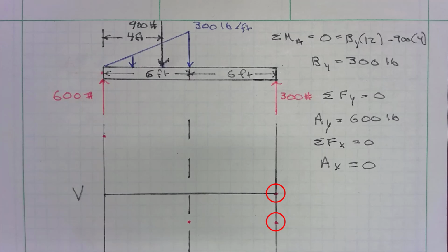All right, so at this point, we have to decide how we're going to draw the lines for the shear diagram. And we have to take the cues from the shapes above, that the loads are being applied there. So if we look at what's going on there, we have a triangle. And what this triangle represents, think of it this way: the value of that force acting on it is going to be a result of the slope of that line.